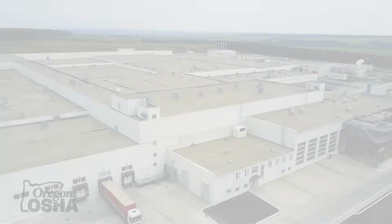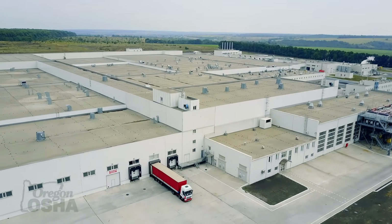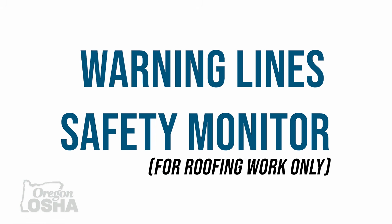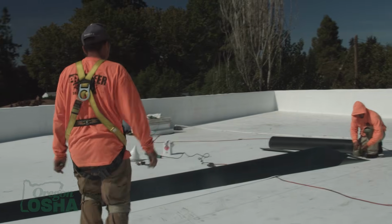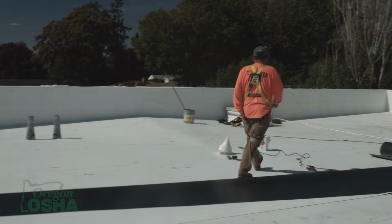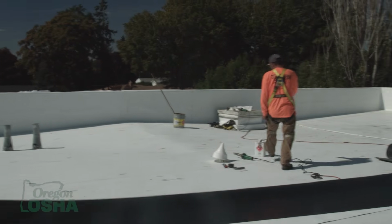In this video, we'll briefly cover 2 options that are only available as fall protection on low-slope roofs. These are warning lines and safety monitor systems. You should think about using these options when there's a situation where you cannot eliminate, prevent, or control a fall hazard on a low-slope roof.